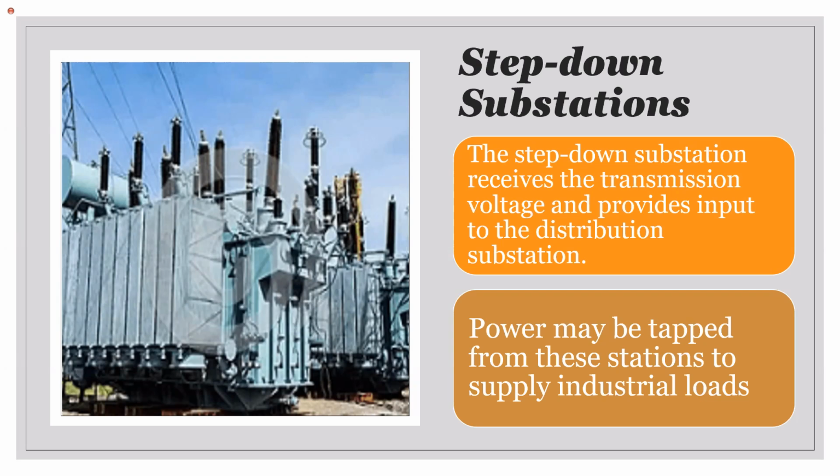So those are going across country. If you look, you see the lines going over the hills. So that's taking some 138. But in terms of, if you want to call it local transmission, then that's at the 69 level. So when we talk about the step down, it will be taking it from the 138 to the 69. But the 69 is not a distribution voltage.